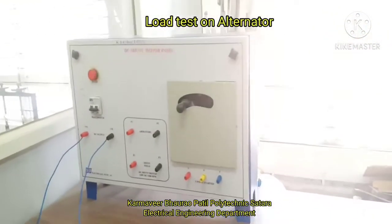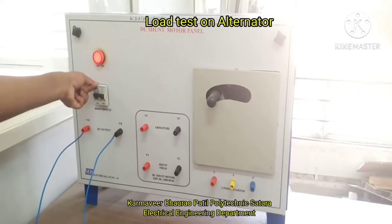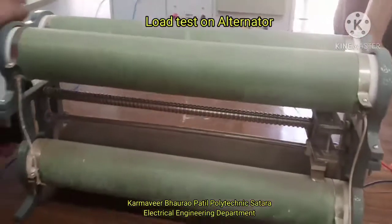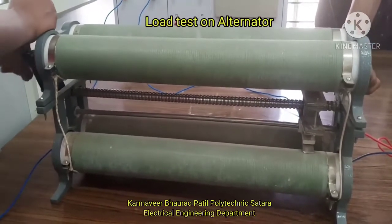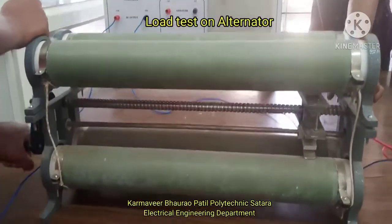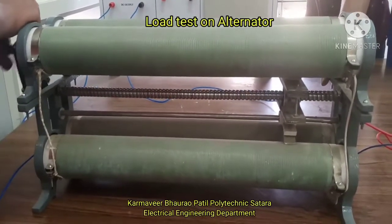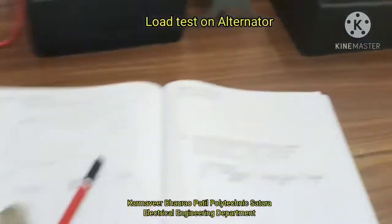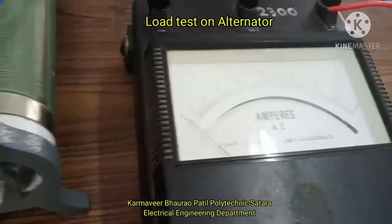After that, the winding of the exciter, and then increase the excitation current. For that you have to change the handle position so that the output voltage will increase. Then we will see the excitation current.